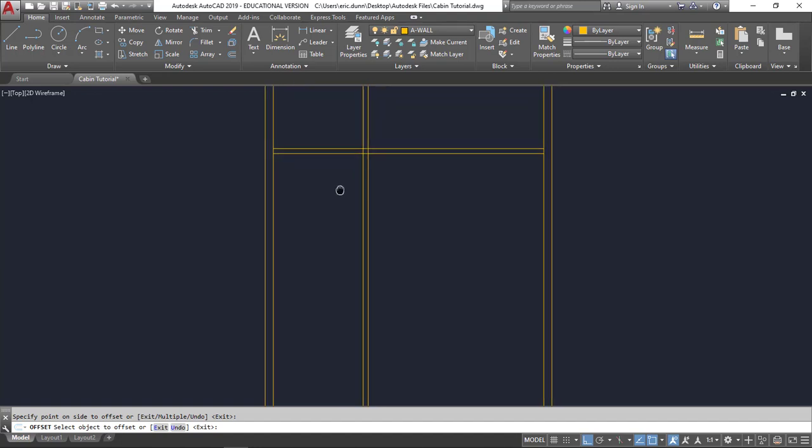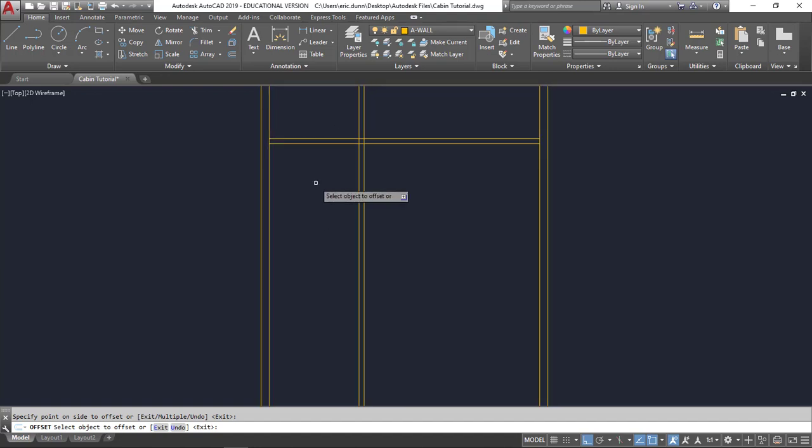All right. So let's put a bathroom in here. It's 5 feet wide, so the tub will fit. Let's make it 8 foot from this line down to this line. So offset 8 feet, enter. Click that down here. I'm going to make my wall at 3.5 inches, enter. And I can either put the 2 tick marks or not, because AutoCAD automatically defaults to inches. So click here and go down.